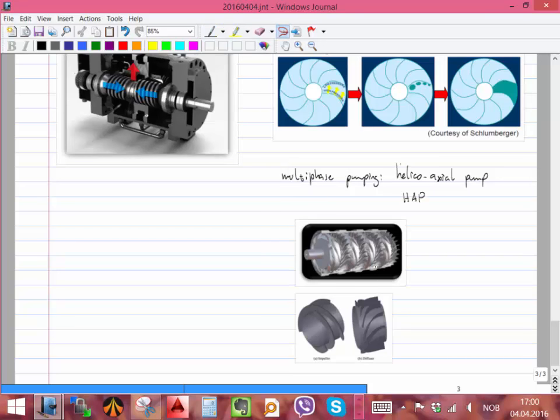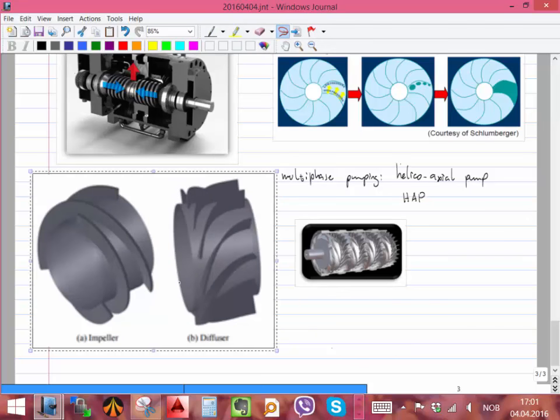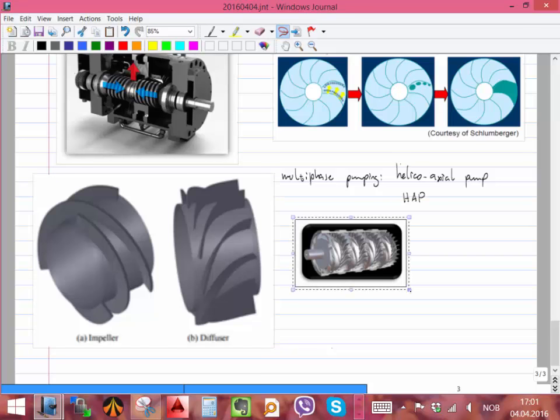And if you see here, this is how the impeller looks like, and you see why it's so twisted. Okay, the fluid has to come from here, and that's the exit, so it's almost like changing direction completely. Okay, and that's because it is the best configuration that prevents the separation of the gas from the liquid. Okay, and then you have a diffuser, and then you put a lot of stages one after the other because it's axial, so we need many of them to provide the delta P that we want. Okay, and this is how it looks like in the arrangement.